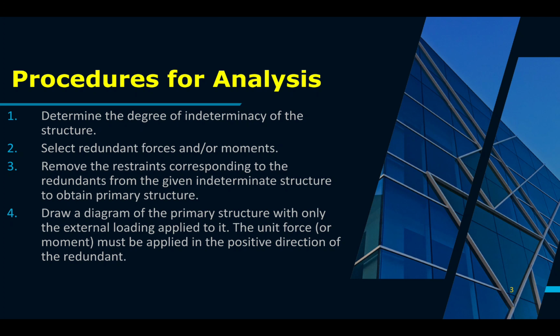Just as we processed our primary structure, we do the same for our redundant structures or our virtual structures. Sketch a deflected shape of that structure and show by appropriate symbols the flexibility coefficients at the locations of all redundants.